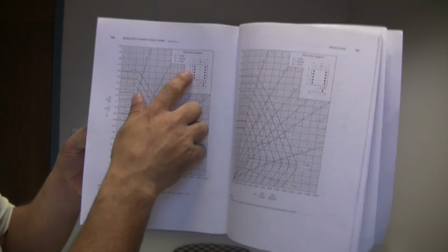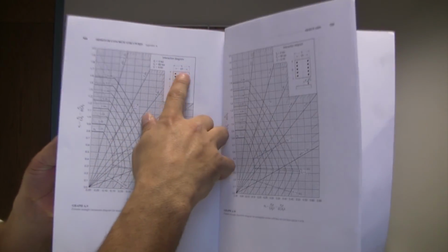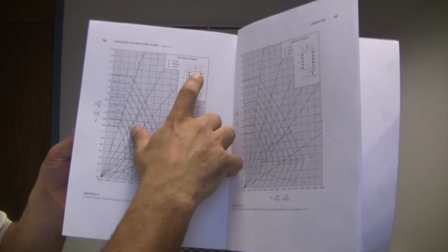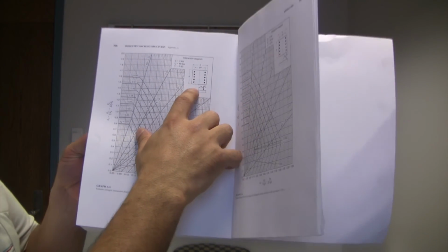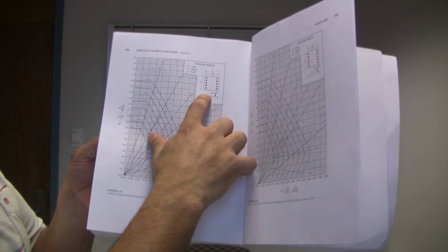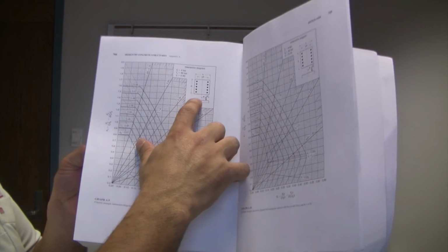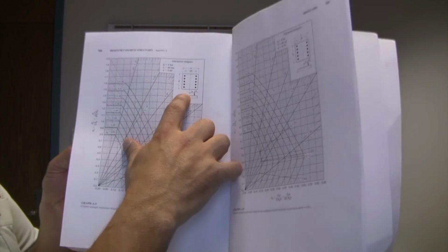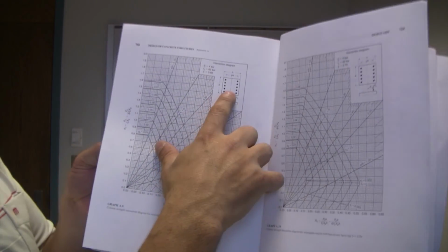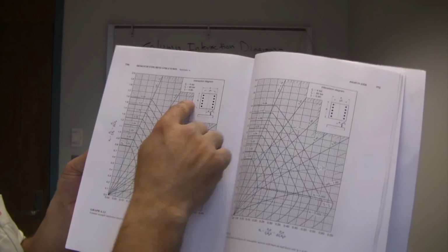Now you go to the second series, when you have something like that, it means the steel is not the same or symmetric on the four sides. So you have to use these for a square or rectangular column when the distribution of the steel is not the same. If you have 6 bars, the distribution will not be the same. If you have 8 bars, it will be the same. 4 bars the same. 12 bars the same. 10 bars not the same. Okay, and again 0.6, 0.7, 0.8, 0.9.